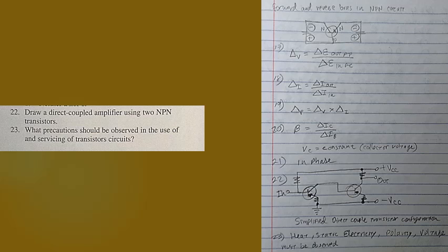And finally, question 23. The last question is what precautions should be observed in the use of and servicing of transistor circuits? And that is heat, static electricity, polarity, and voltage must be observed.